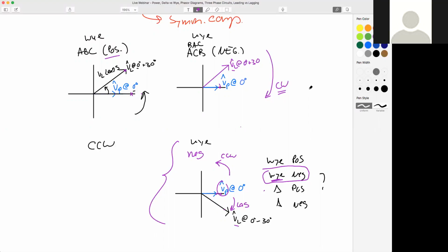Essentially, if you've got any kind of real load on there, you're going to trip a breaker, right? Because if you short, you're going to draw max amps, and max amps that phase can deliver. Well, nine times out of ten, it's going to exceed the rating of the breaker, the trip settings. So you're going to pop that breaker big time. You hope you do. If you've got a protection engineer worth his salt, he set it up correctly, and you're going to pop that breaker to protect that equipment.